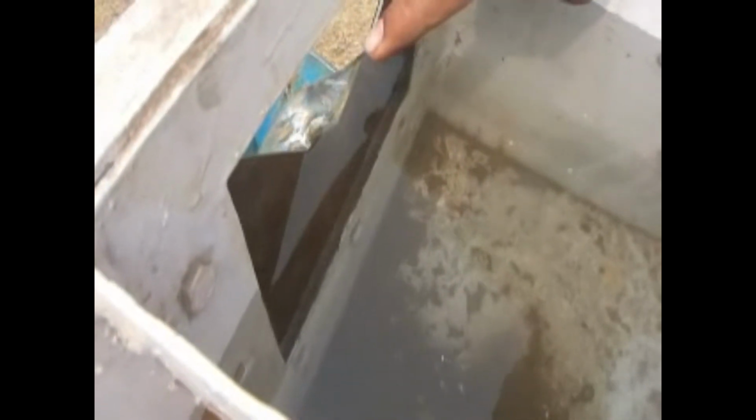And this is basically the idea of baffle plates. Now you can see water is coming out, it is disturbed water, there is turbulence. The moment it is passing through baffle plates here, water has the least disturbance. Now it is going to this outflow chamber, and you can see here the level is reduced. However, this flow occurred because of a level which is much higher than this particular point. So we are measuring at least 4H away from the crest, the head of water which is causing flow.